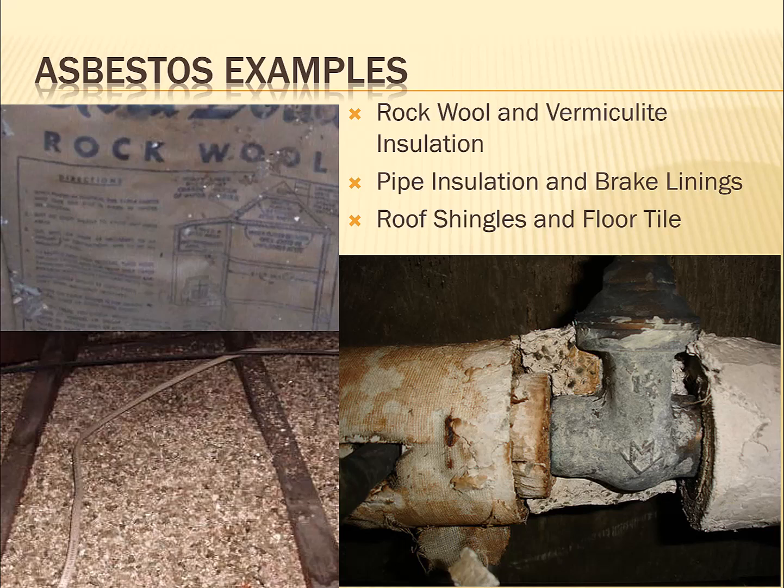They'd have a spray wand in there and soak it as they massaged it to break it up in the bag, spraying the whole time to get the dust down to nil. They would literally seal it up, break it all up, and wash it off while it's all still contained in the bag, and remove it.